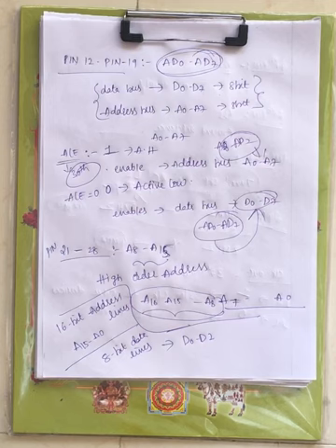The lower order address is multiplexed with the data lines. Depending on the ALE signal, it is decided whether the lines carry the lower order address or the data bits. From pin number 21 to 28 we have address lines A8 to A15, which carry the higher order address.